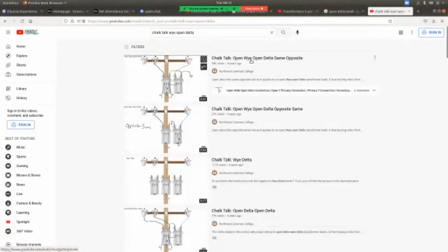Why did they say open Y? Any guesses? How many phases am I using out of 3 phases? 2. So that's why they're saying open Y. I'm not using all 3 of the Y primary phases.